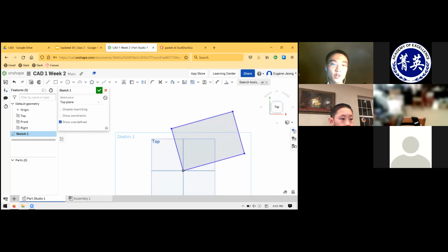So the way that we introduce real life numbers, things like inches or centimeters, into our sketch is through the use of this tool, which should be directly to the left of those relation tools. It looks like this. It's where my cursor is. It's the two lines, and there's the forward backwards arrow that indicates the distance between those two tick marks. So that's the dimension tool.